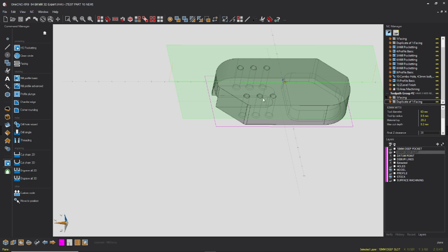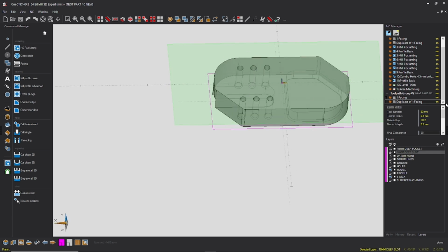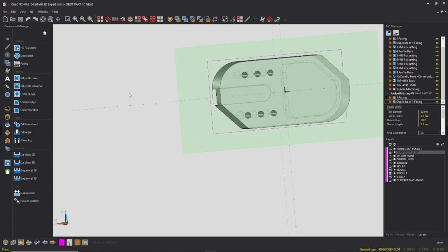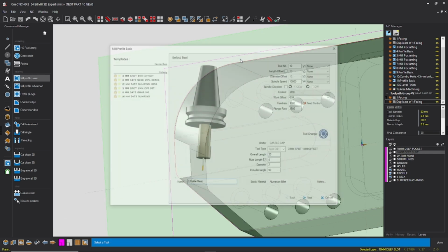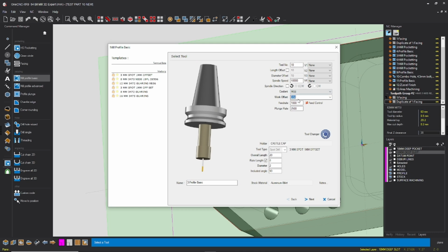Now all we've got to do is deburr and spot the holes. We don't want the deburr lines because they're different to this face, so we're going to use our profile lines. We'll come in with that tool that we just used, the 3mm spot, grab that down there, go that side like that, click F3. Yep, all looks good apart from the G54, click G55.